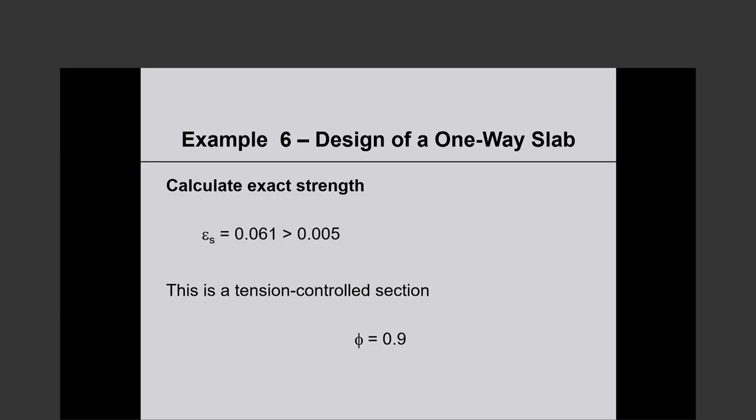And code does not prescribe any maximum strain in tension for tension control beams. Is there any best practice to follow? So what he's saying is epsilon sub t, 0.005 onwards, it's all tension control. Is there an upper limit? Is there any good practice to follow? That's what he's saying.